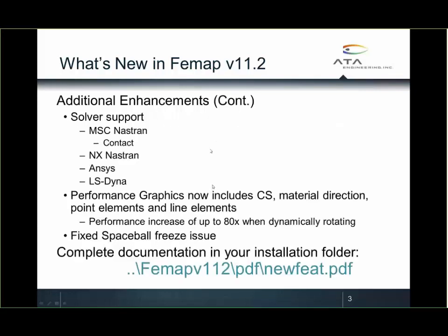That's a new option. They've added a lot of solver support, particularly for MSC Nastran and contact in MSC Nastran. Some additional options they've added in NX Nastran, ANSYS, and LS-DYNA. They've enhanced performance graphics to work with coordinate systems, material directions, point elements, and line elements. And they've also increased the performance of performance graphics when dynamically rotating, a few other options there.